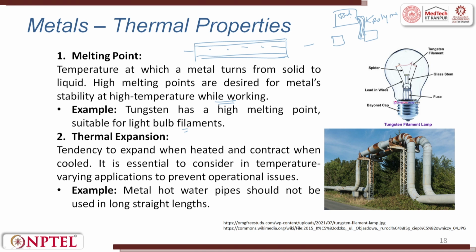The other important thing is, when you are trying to take a lot of hot water, you should always have bend portions, because if you have a long lengthy pipe, it will expand and it will contract. So, the connections might get broken.